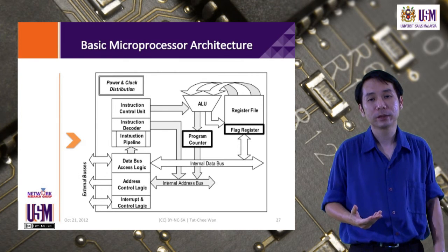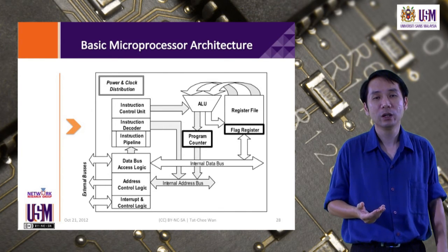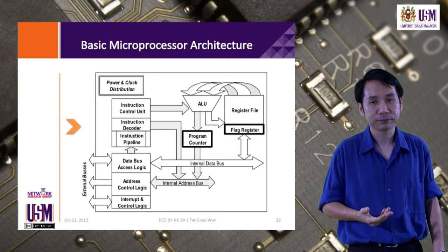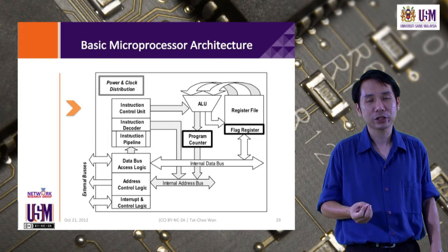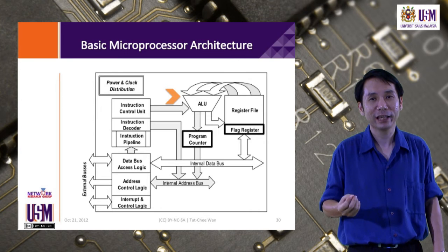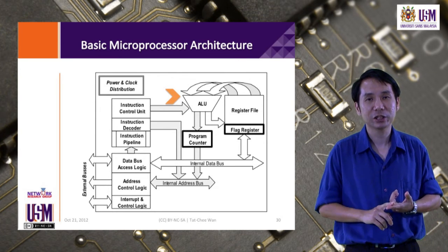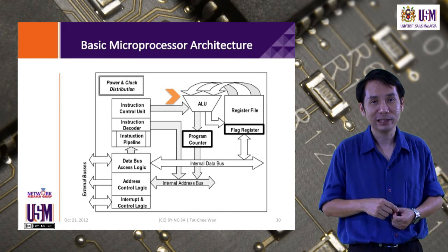the processor. The instruction decoder then processes the instruction to determine what other variables or operands are used by the instruction. And finally, the instruction control unit will take the instruction and perform or command the arithmetic logic unit or ALU to perform the actual instruction, whether it is addition, subtraction, division, or some other calculation needed.